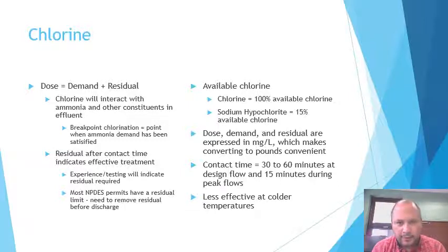So the operating principle in using chlorine is to feed enough chlorine that after the contact time, and chlorine does take a fair amount of mixing and contact time to be effective, at the end of that contact time, you want to have some residual left over. And if you have residual chlorine left, then that generally tells you that you've fed enough to get adequate disinfection.